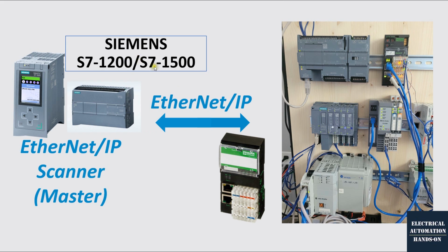And in this case, I will introduce the Siemens controller running as a master. This fits the following scenario. For example, in this picture, my controller is a 1500 or 1200 controller, and the main system is a PROFINET system, Siemens ET200SP or other PROFINET devices. But maybe you have some devices, for example a barcode scanner, printer, heater, or some VFD devices. They could be Ethernet IP devices. So how can you communicate with them? In the past, Siemens controllers could not directly communicate with them, unless you used some bridge from PROFINET communication to Ethernet IP communication. But now, using the feature I'm going to introduce today, you can communicate with them.